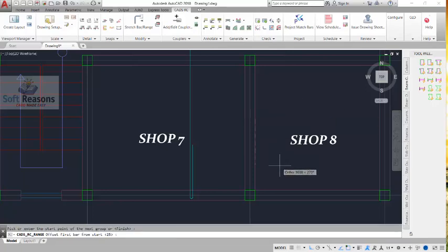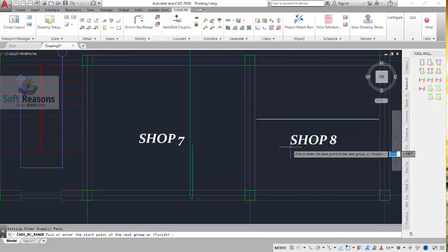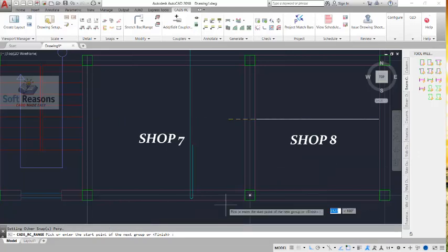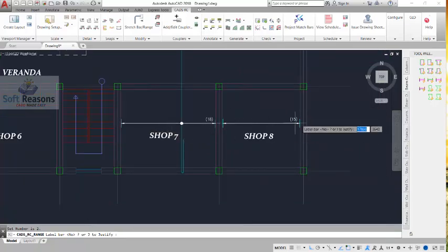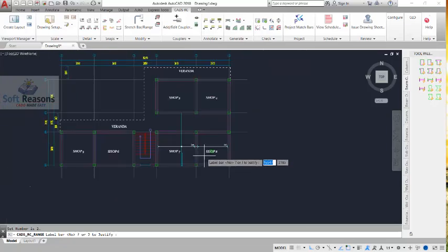So once you pick that point, it will ask us for the offset again, which is 25. It's already existing as I've keyed in the previous provisions. Enter. All right, all the way to this other provision, click again, and then the 25 is still existing, or you can still key in the 25 right there and enter. So after which enter again. All right, so you also have to proceed to enter in order to finish. Always be checking your command line so you can see the information right there. Enter again and enter. Right, so you now have this, so you can now see the way it's being identified, okay, all through the two panels successfully.